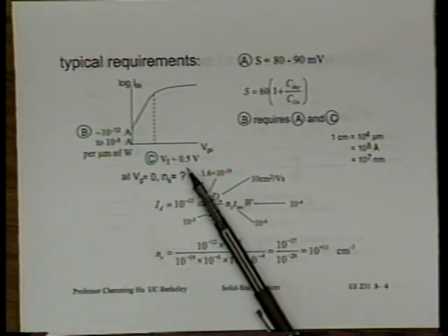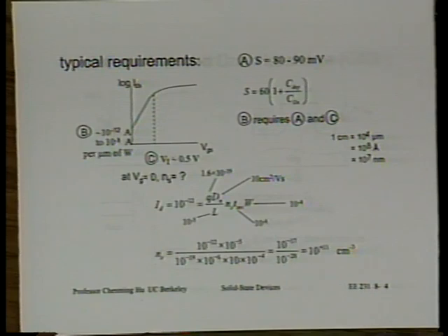But because the number of those transistors is small, if each of them takes 1 microampere, it doesn't matter too much. You see what I'm saying? If the other 100 million transistors take very low leakage current, these 100 transistors I can allow to take 1,000 times larger leakage current. Is that right? So this is the concept of multiple VT technology, right? That's not too expensive to do. And so things like that are beginning to come online, all right? But we're right at the juncture when these are beginning to come online.